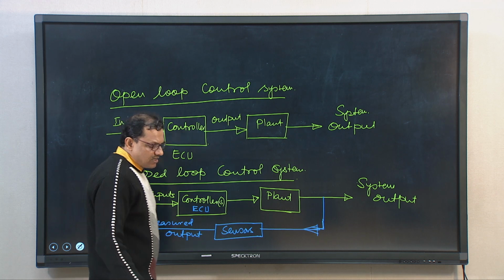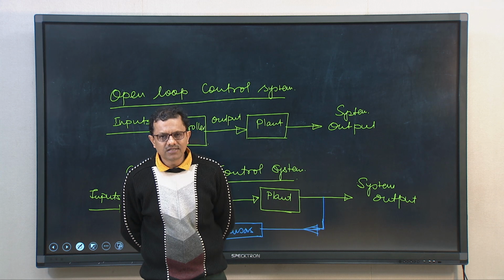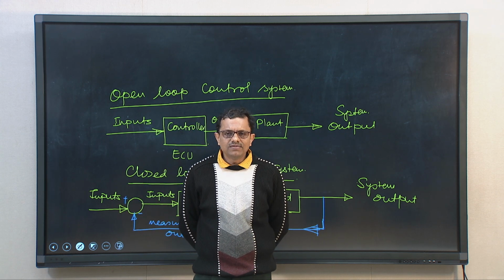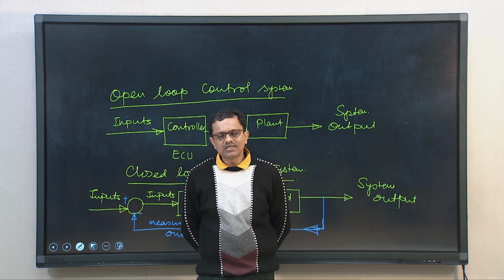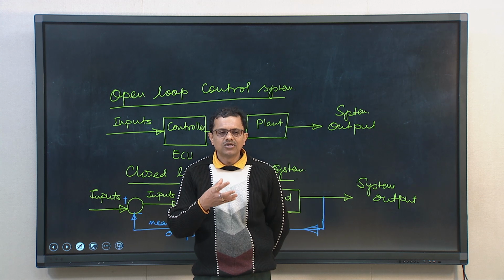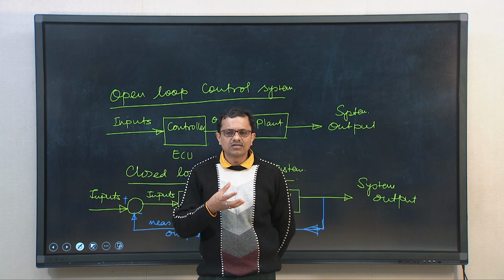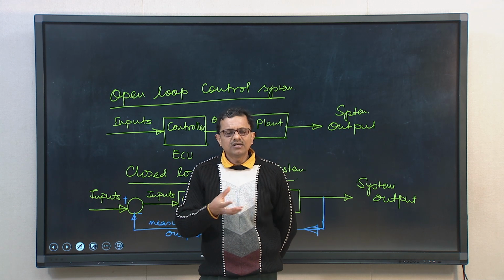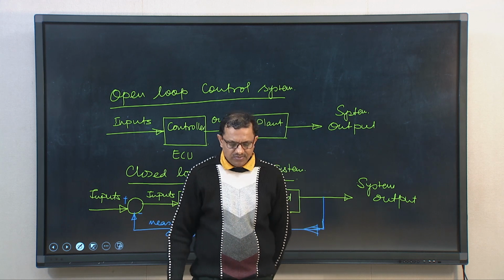As I said, the electronic control unit or engine management system or ECU will receive signals from the sensors, and upon receiving signals, ECU will be able to process the data and then generate control signals for the actuators, because essentially the actuator will be responsible to bring some corrections so as to supply the required quantity of required input so that the engine can always run at its optimum condition.